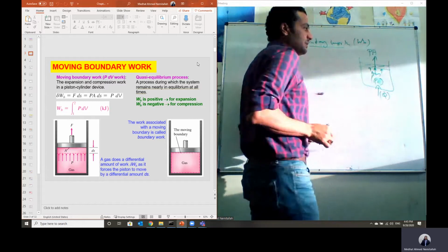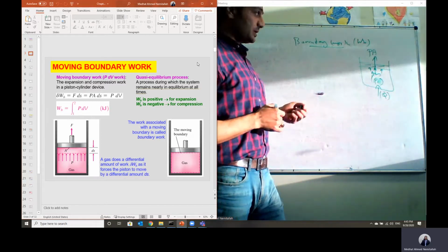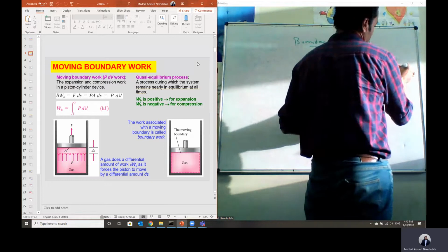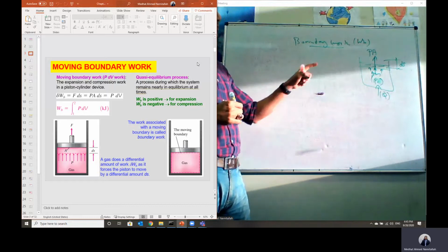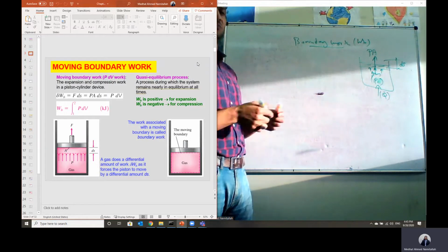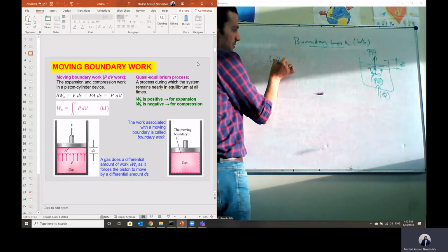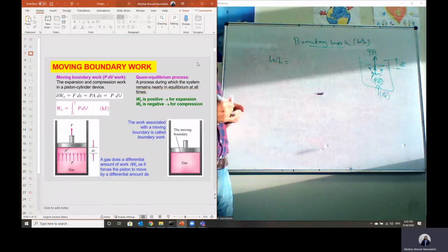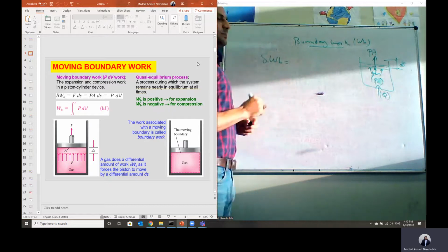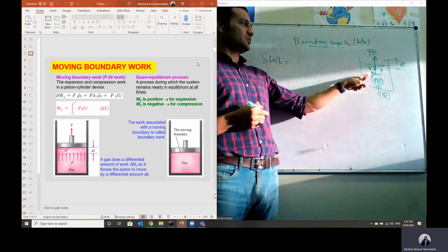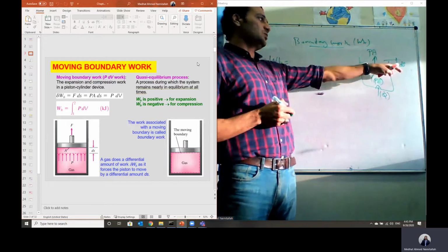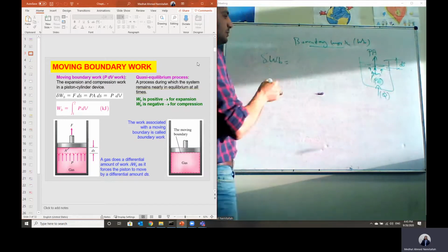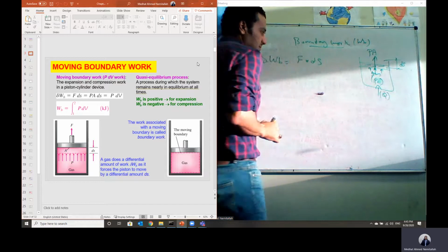It will equal the pressure multiplied by the area, the cross-sectional area of this piston. Due to this increase in pressure, the piston can move a distance, let's say delta S. As we have an applied pressure force and we have movement, then we have work. This work is called the boundary work because it is the work associated with the movement of the boundary. We call it delta boundary work, because we assume a small amount of heat added, so we have a small pressure rise and a small distance movement delta S. So delta boundary work will equal the force multiplied by the distance delta S.